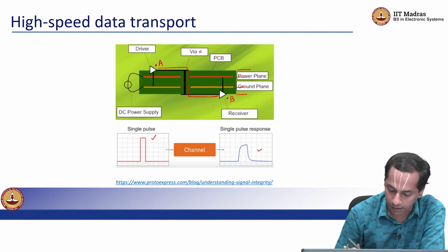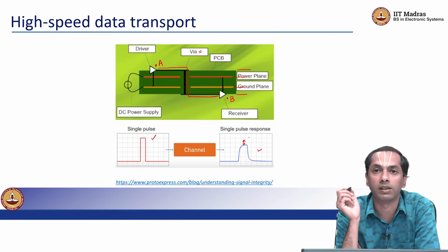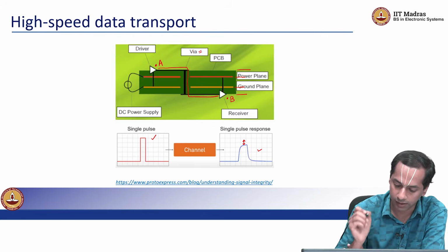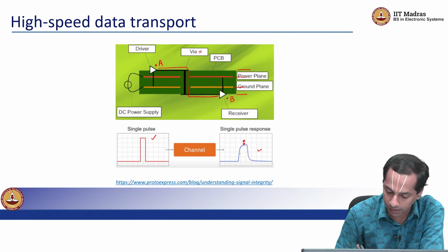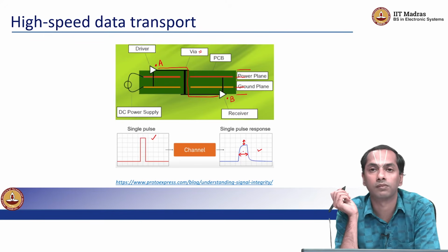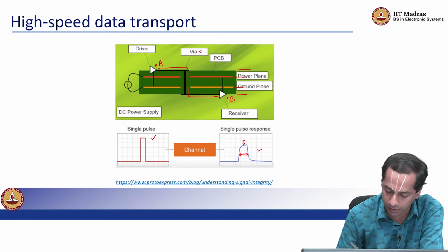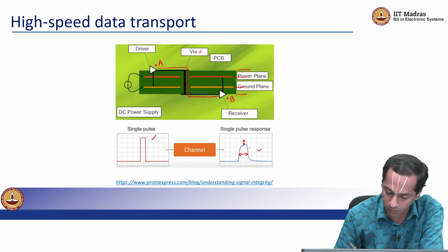So, what are the things I can observe? One is, even though there are no scales on the two images of the oscilloscope data, we can say that the pulse is stunted, right? So, the height has reduced. Another thing you can say is the pulse has also broadened. Okay. Some observations that we can make are the pulse height seems to have reduced, the pulse width seems to have broadened, and I also seem to notice that